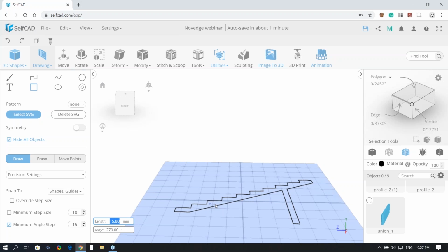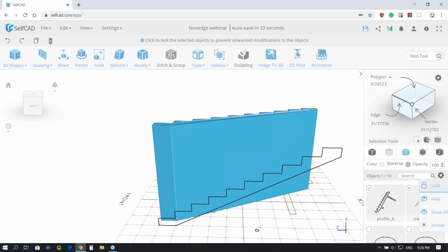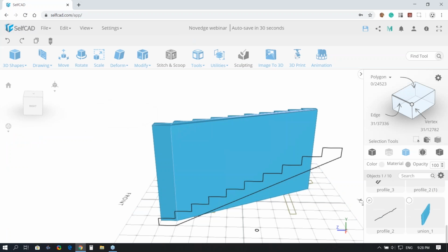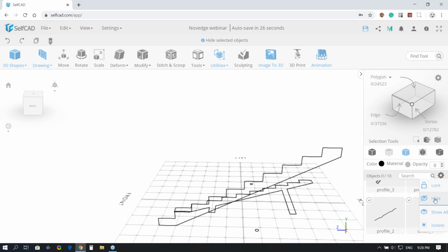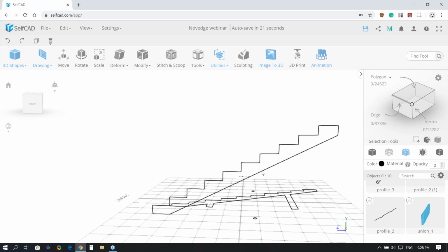And now we're going to go to the eraser, and I can use a rectangle, which I'm just going to snap from this point to simply erase like this. So you see, I get it straight. If I would use normal drawing, I would have to make this with a few clippings, and also you can flatten this, which is quite an interesting way of doing it. So now I can get rid of the other object to hide it out of the way. Let me deselect everything, select this, and hide it. I need to hide this object as well.